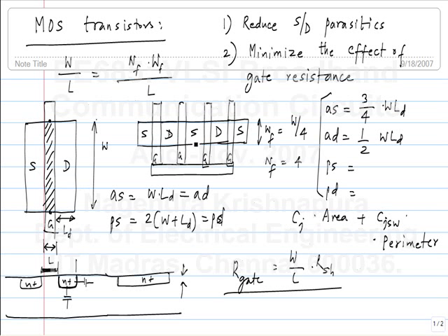What is it in this case? So each of these gates has a resistance of WF by L or W by NF by L times RSH, and you have NF of those in parallel, so it gets further divided by NF. So the gate resistance goes down drastically as you split it into a number of fingers. Okay. It's based on those things that typically you use 1 or 2 micron fingers, but in some cases you may have to do something even narrower than that. Okay. So this is just some practical information.